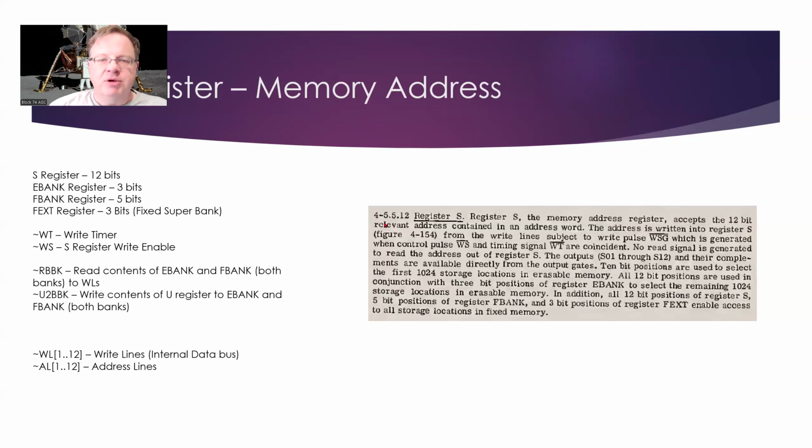So the Apollo Guidance Computer makes use of banking. It has a fixed set of memory that's always addressable, and then it swaps in and out banks of memory depending on what you're doing, and uses that in order to address the entirety of the memory as a whole.